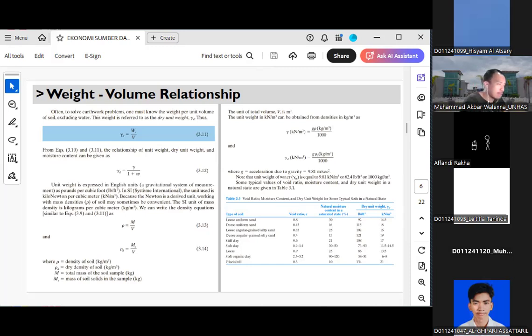Okay, and I think comparing the granular to fine grain, and by fine grain I mean the clays, clays definitely have a much higher void ratio, and the number can be double or triple in comparison to granular soils, and the drying rate is usually lower in comparison to sand and any granular materials.